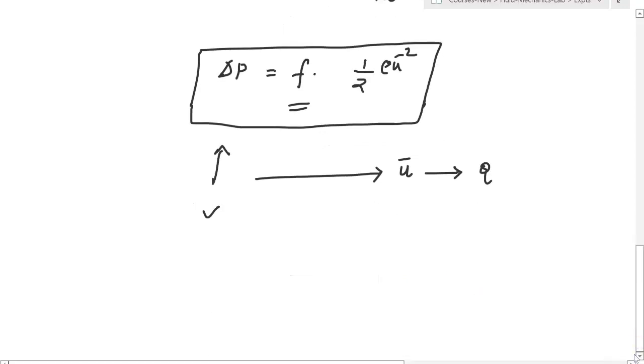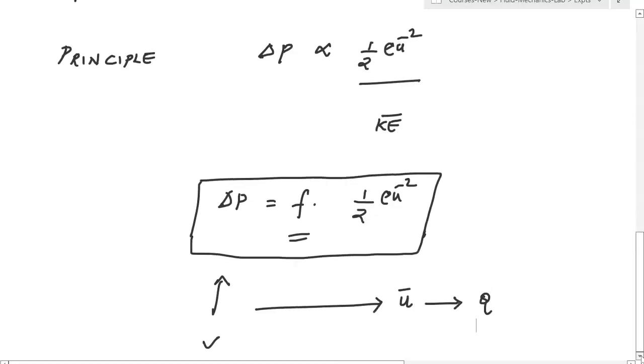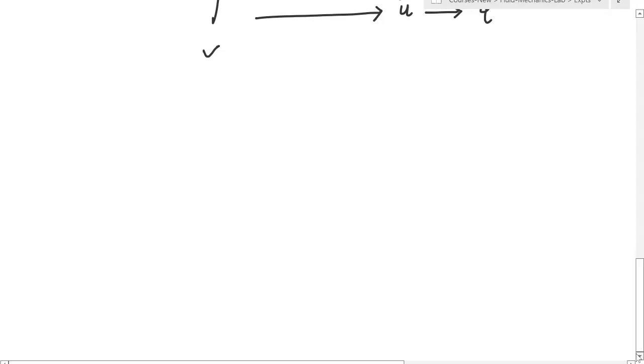Because for a homogeneous, single phase flow, pressure drop and mean kinetic energy are uniquely related. But if you need to use this, you need to know this proportionality factor. So you need to know this coefficient for that particular setup. This coefficient in head meters such as Venturi, Orifice and flow nozzles is called the discharge coefficient.